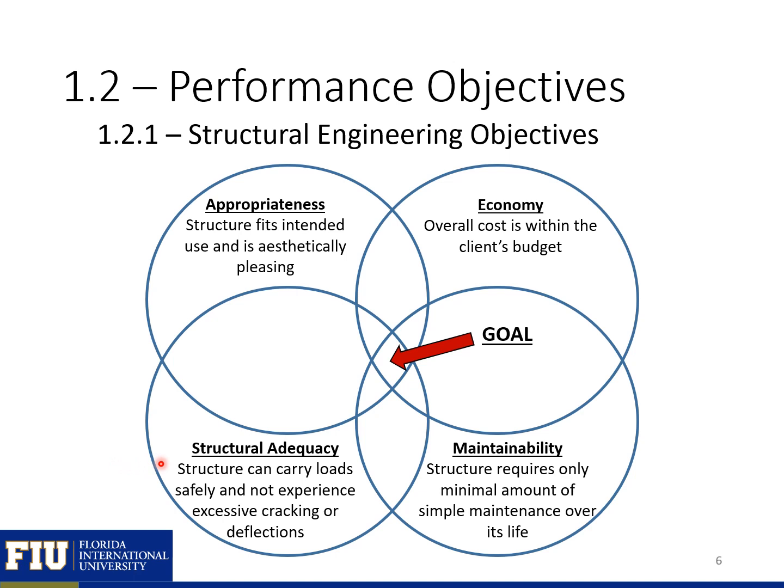Structural adequacy. So a structure needs to be able to carry loads safely and not experience excessive cracking or deflection. So this will be the primary focus of our course, designing our members in our building or bridge to carry the loads so that they won't experience excessive cracking or deflection, so serviceability, and they'll also be able to carry ultimate loads safely, so strength considerations.